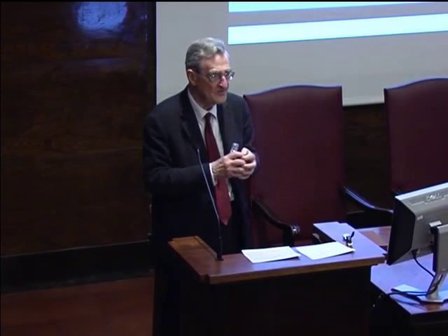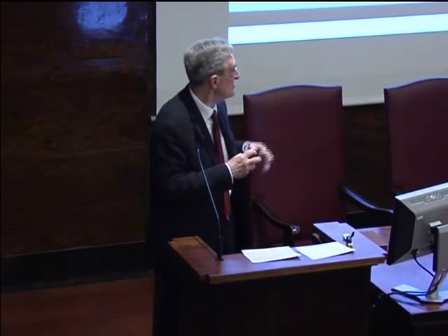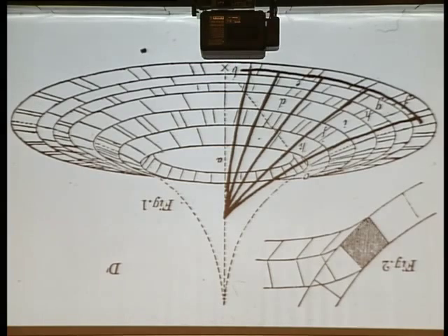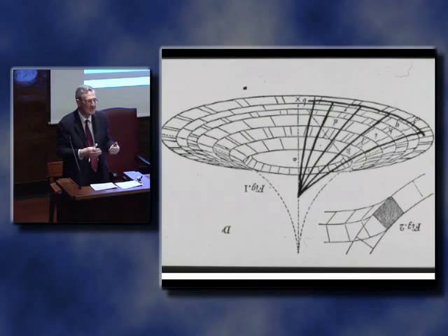You cannot remove that centering. So, in building a fan vault, you have to have extremely complex centering, which cannot be removed until you have completed the whole structure from both sides and going down the building, and the components start interacting. Only then can you remove this expensive centering and take it away.